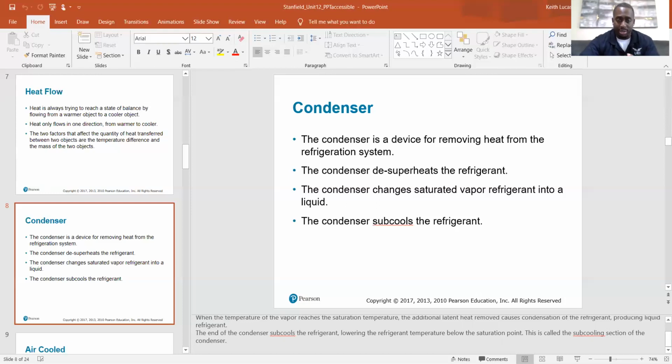and then that heat that is transferred from the refrigerant to the air is now blown out through the top of the condenser and just released into the atmosphere, which is another reason why the condenser goes outside, because we're removing heat from inside and we're dumping it somewhere where it doesn't matter, which is outside. We don't care. It's already hot outside. So we're dumping the heat out there and we're removing it from inside so that we can be comfortable indoors on a hot day.